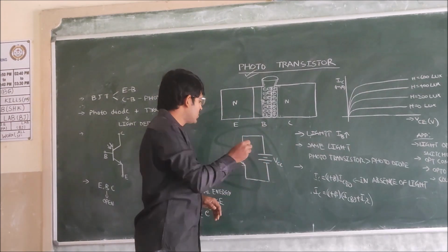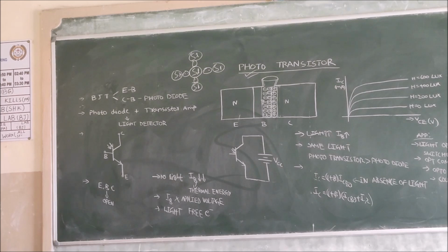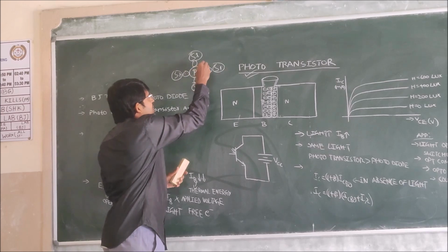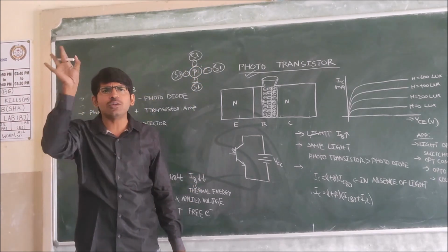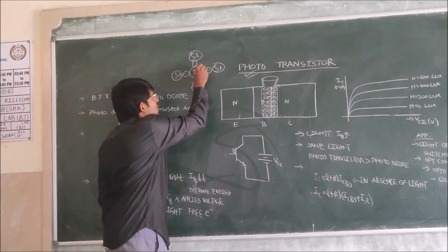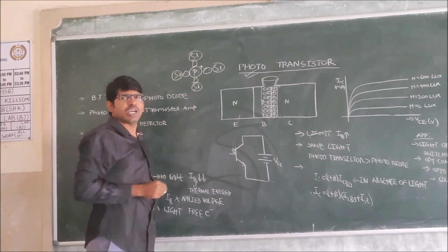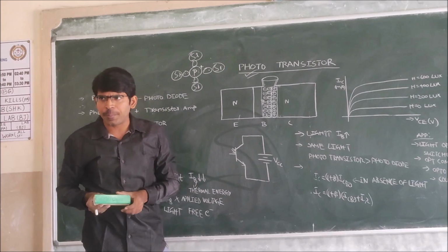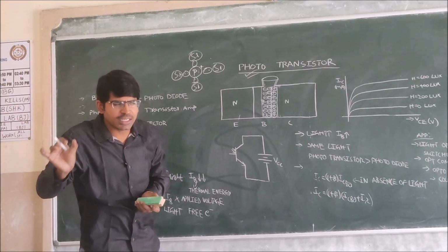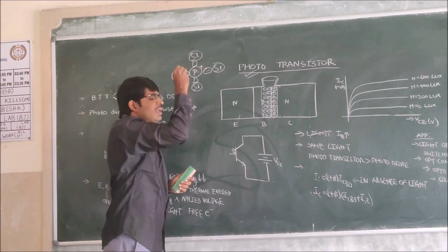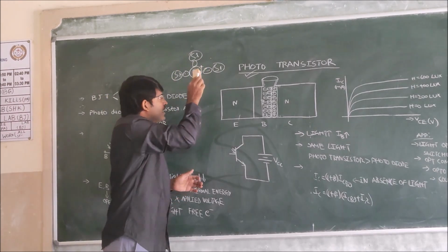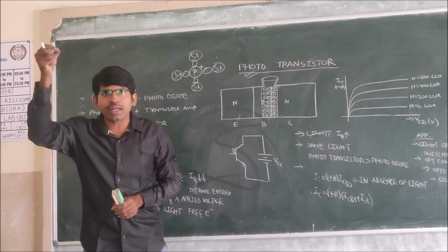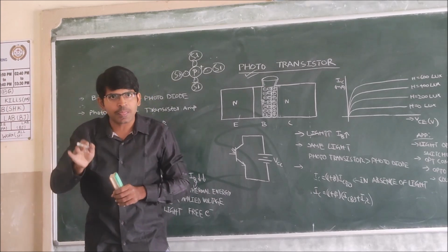So this is the normal silicon structure. When we represent the positive ions, we say phosphorus is replacing the silicon and donating one electron. That is why phosphorus gets a positive charge. Only these positively charged ions are there on the N side. When the light is incident, the electron in this covalent bond gets energy and comes out. Because of what factor did the electron come out? Because of the light energy.